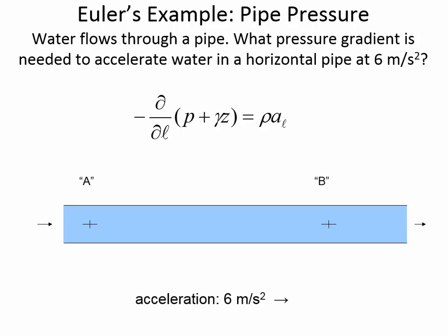This isn't. The pipe walls are parallel here, and so the fluid is not changing with respect to position, and that's the definition of convective acceleration. So if it says it's accelerating to the right, we can tell just by looking that's a local acceleration. And what the local acceleration is caused by is unsteady flow. So someone, maybe at a valve or a pump upstream, is opening the valve so more and more water is going through that pipe. And so the flow rate is increasing, and that's what's causing the acceleration. The velocity through the pipe is increasing over time. So this is a local acceleration. Because it's a local acceleration, that's why we're applying Euler's equation here.